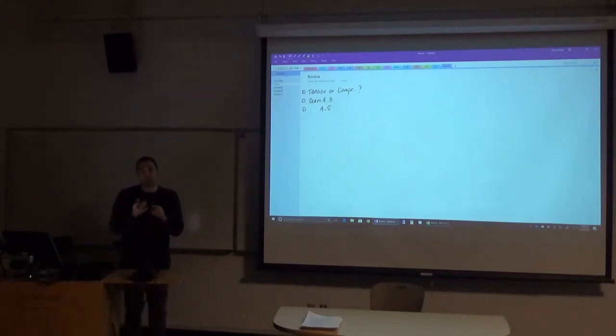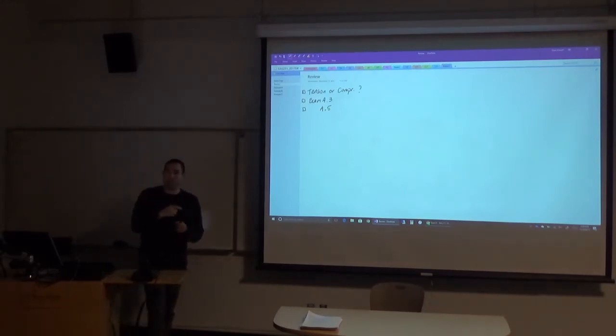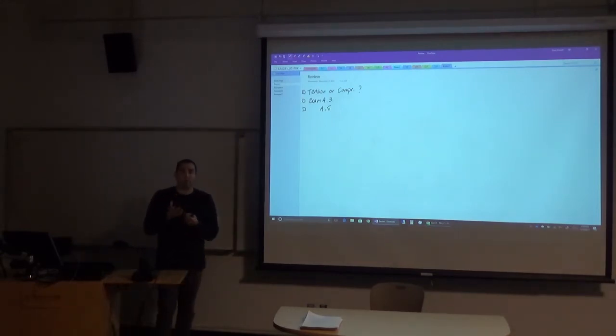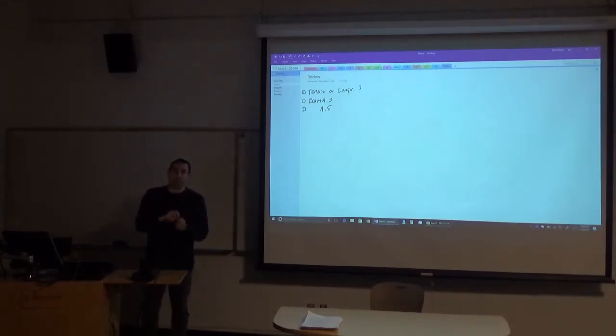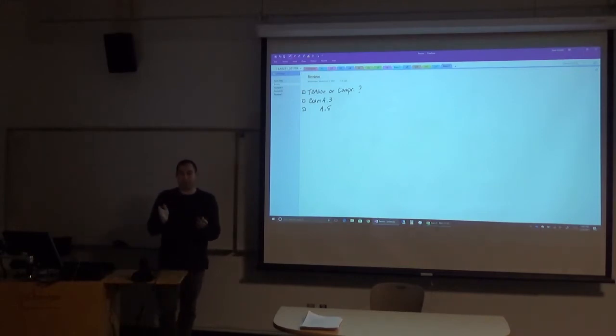If you remember, in a truss all of the members are 2 force members, so we know the direction of the force in each member. A frame or a machine has some of those components, but other components are not 2 force members. It usually has pins connecting different parts of the machine, and you have to identify which of those you know are 2 force members, and then you make a section cut right through it. So if there were 3 problems on the exam, and I'm not saying there are, those are the 3 main topics that we're going to cover.